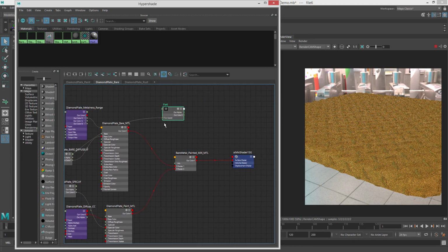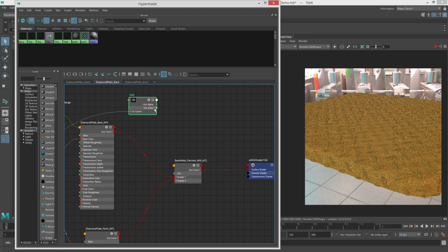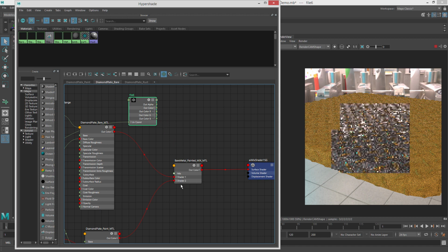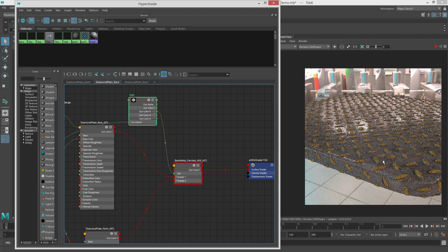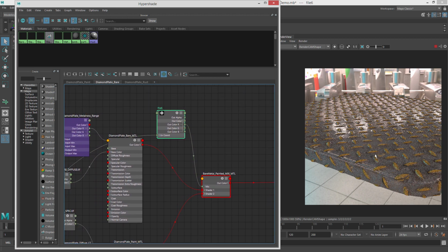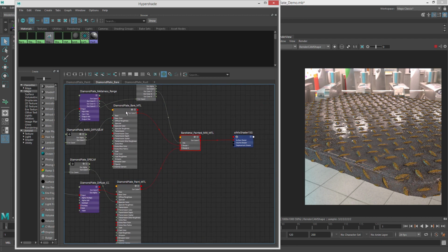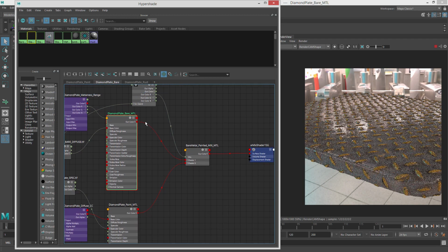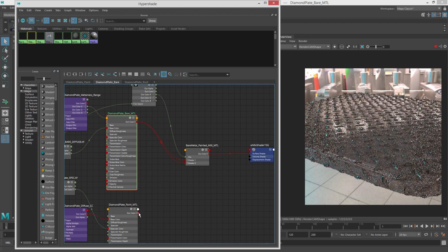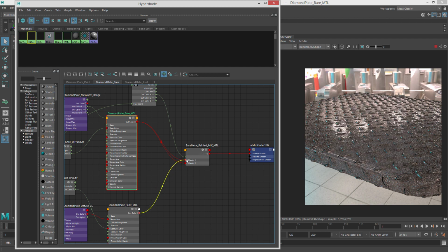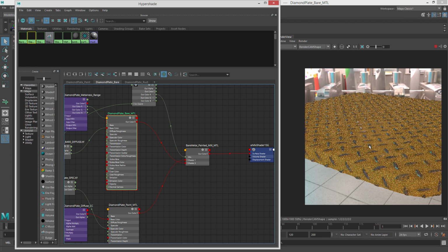And what I want to do is, because this is green, I want to use a single channel to mix in here. So I'll take the red channel, and you can see now it is mixing. There's two ways that I can flip this, because I want it to be inverted the other way. I can either invert this image, or I can change the order of how they're mixed. So if I took the bare metal, put it in shader 2, and then took the painted metal and put it into shader 1, it should flip the order like that.